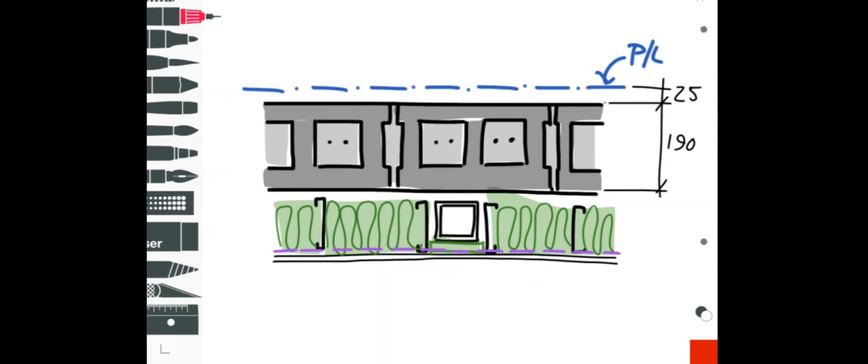I have certainly seen it done that way. Basically, it's like a basement wall in a house, except it's even worse because you're using metal components versus wood components, and you're going to have more conductance through the metal, and more heat loss through all these metal components, not to mention, of course, the beams above as well.